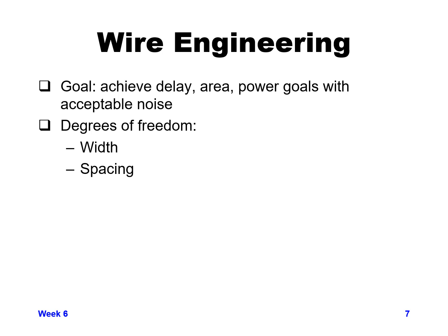But if you use all wide wires with wide spacing, you get very few wires, and you might get a lot less number of wires than you need in order to wire up your design. The other thing to keep in mind is while a wider wire is good from a lower resistance standpoint, the wider wire will have more capacitance to the layer above it and the layer below it. And so not always is a wider wire a lower total delay.